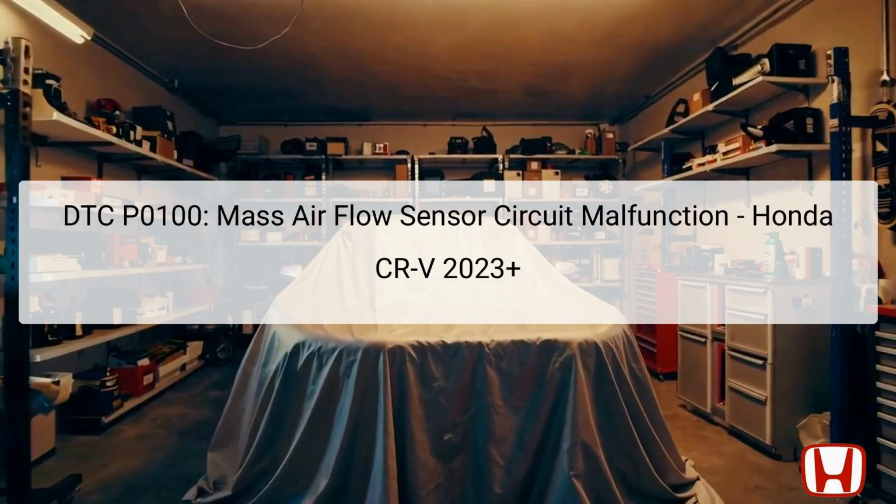When the MAF sensor output frequency drops below a specified threshold, it triggers a fault, leading the PCM to store this diagnostic trouble code, DTC. This malfunction can have various consequences on engine performance, including poor fuel economy, rough idling, and decreased power output. We will delve into the error description, potential causes, and a systematic troubleshooting approach to effectively resolve this DTC.